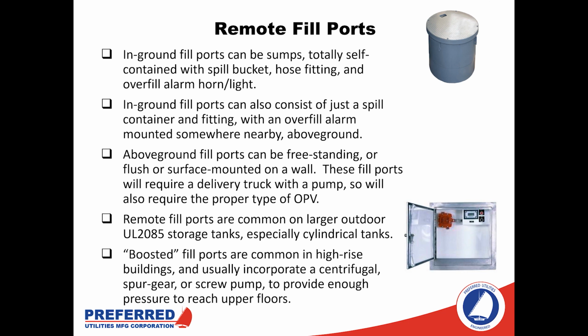And these can be installed in ground, in wall. They can be set up for gravity fill or pumped in fill. Now, the important thing to note about this piece of equipment, at a minimum, what we should be looking at is an audible and a visual alarm. And the audible alarm will come on immediately once high level is reached in the main tank to indicate to the fuel delivery person that they need to stop providing fuel to the tank.